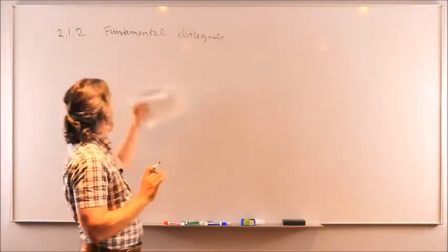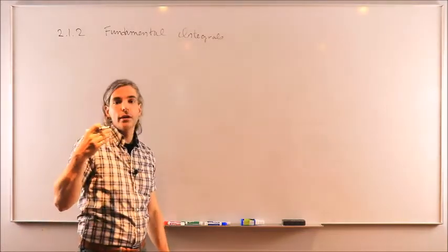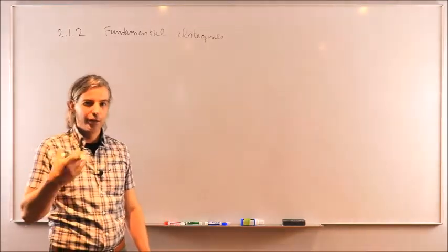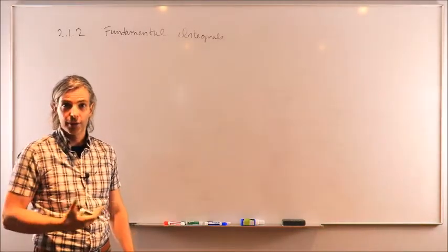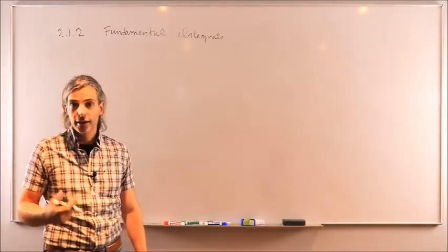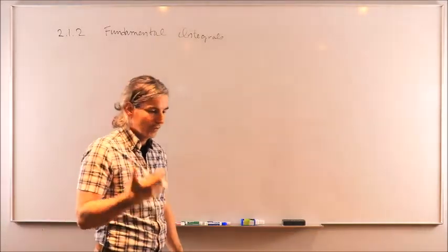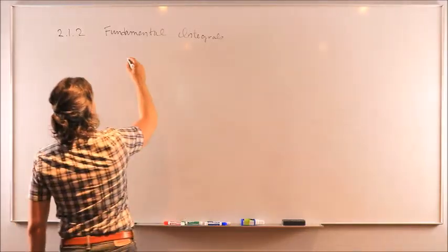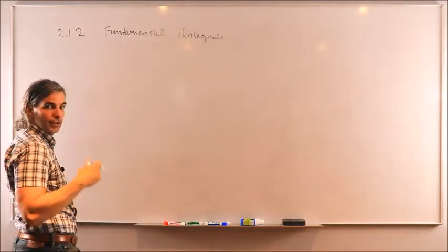Or in other words, those fundamental integrals, or things that are not going to vary with time, are only valid under the two-body problem assumption, which is, again, a theoretical situation because in practice, there are other planets affecting the spacecraft motion, but there are also perturbations, as I just said, drag, solar radiation pressure, tidal effects, gravitational perturbations due to the oblateness of the Earth, and so on and so on. So just keep in mind that those things that aren't going to change with time are only applicable under this theoretical assumption.